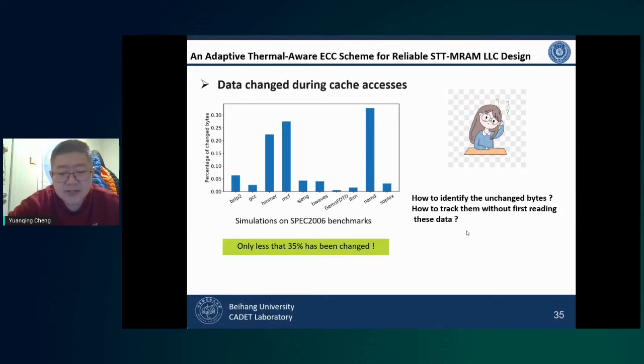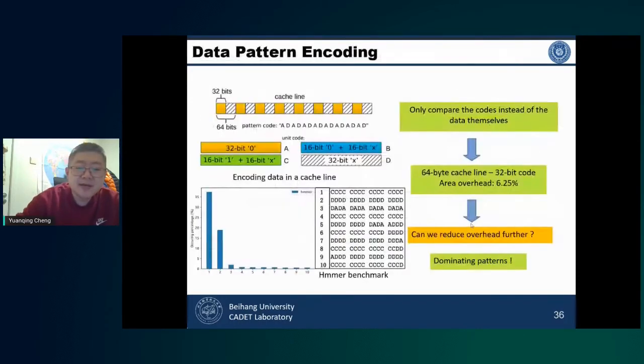This write behavior will degrade the microprocessor performance more severely. In our work, we try to write the unchanged bytes without reading the original data back. To achieve this, we use a different coding scheme, and we try to identify 4 different scenarios.